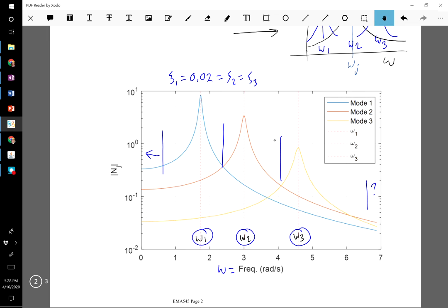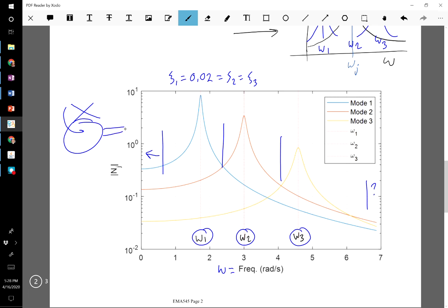Helicopters actually have a rotor that spins at a constant speed. So that rotor on the top of your helicopter, here's a little Harold the helicopter, right? That rotor actually spins at a constant speed, and you vary the pitch of the blades to vary the amount of thrust. And the reason for that is you choose the operation speed to be at one of these magical frequencies away from any resonances of the helicopter. If you don't do that, you could hit a resonance and destroy the helicopter.